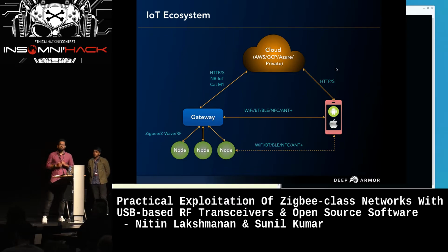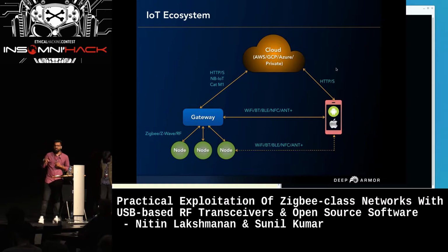In the home automation system, we will have nodes which collect sensor values like temperature, security alarm and more. At regular intervals, these nodes will send the information to the gateway that is deployed in the house. It will be using lightweight protocols like Zigbee, Z-Wave, RF signals. Once the data is received, the gateway will send information to the cloud through HTTP protocols.